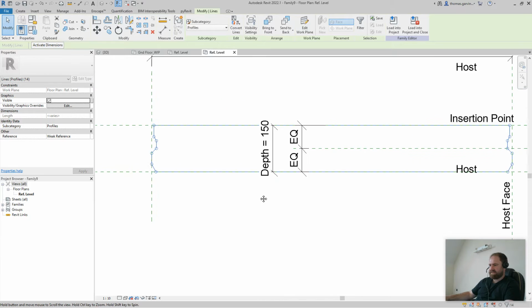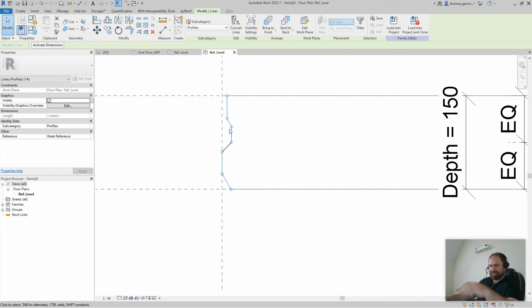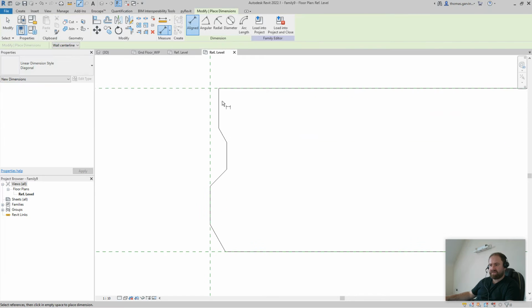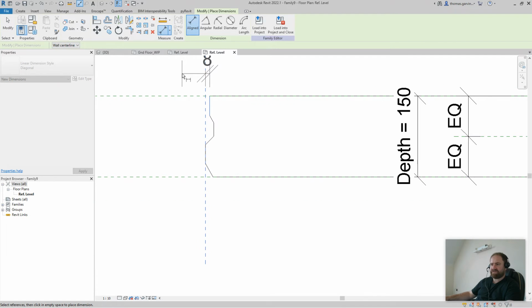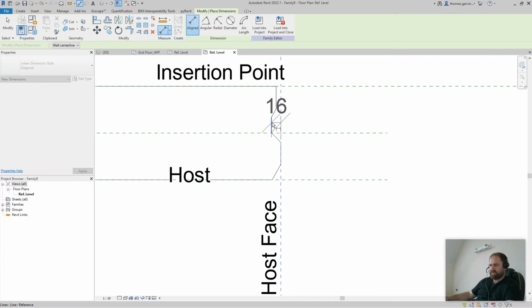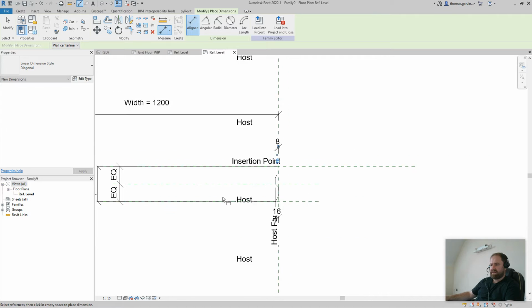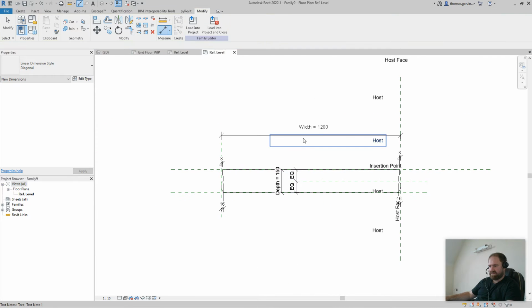part of it's hitting the reference planes on the left and right, and towards the bottom segment, let's say, and the top segment is off the reference plane. So I'm going to just dimension lock those because I'm not going to bother making a parametric. Just going to dimension lock that and dimension lock that vertical, and the same over here. Lock, lock. And I'll just test that to make sure that all moves correctly.